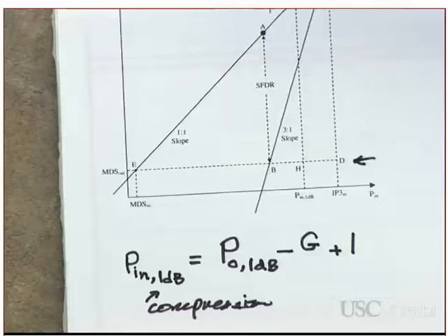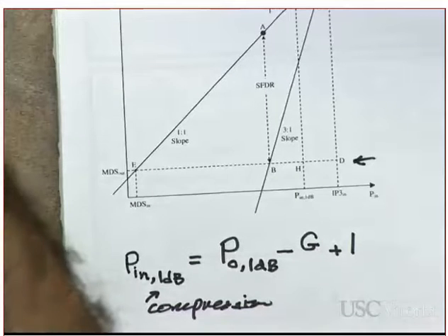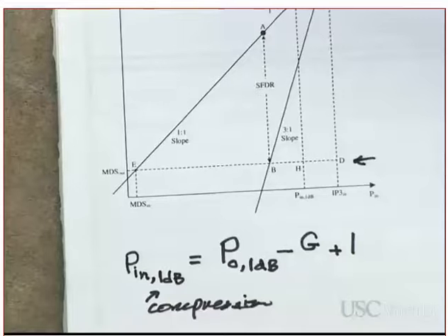What is a dynamic range? Sometimes they call it the linear dynamic range, and sometimes they even call it the 1 dB compression dynamic range, to emphasize that you are looking at the point in which the amplifier starts compressing by 1 dB. Did you get this or not? Okay, now listen to me.